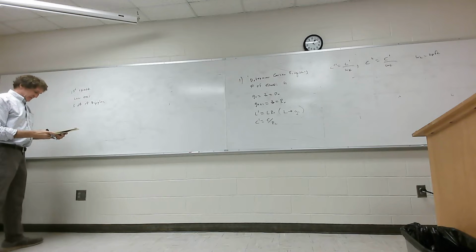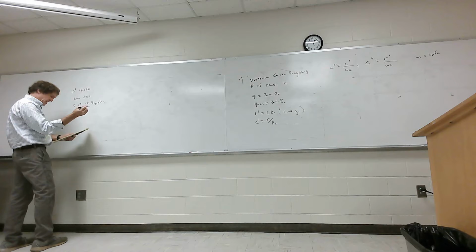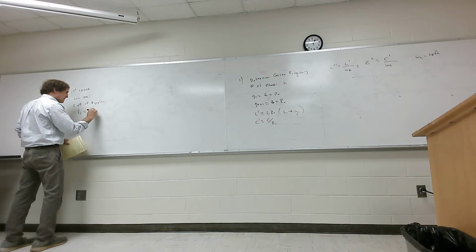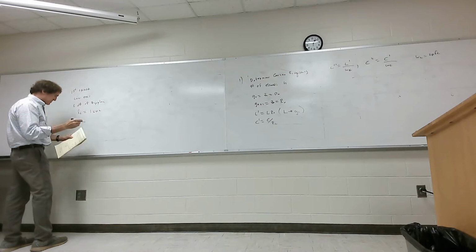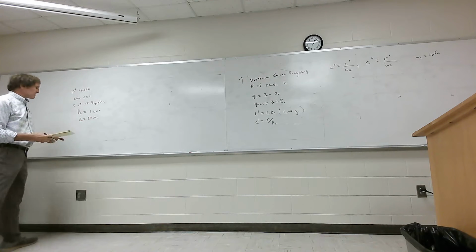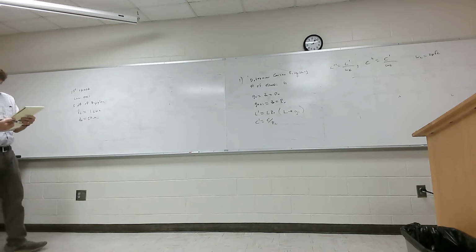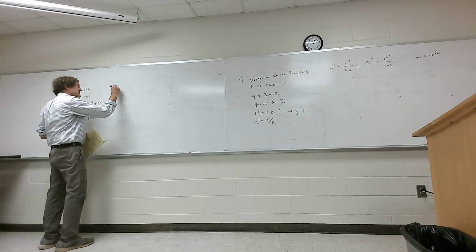I'll explain what ripple is in a second, but you probably can guess. And he wants the cutoff frequency for this to be 1 gigahertz. And the characteristic impedance of this is 50 ohms. So it's 50 ohm source, 50 ohm load. First order means one element. When they say order, it's the value n, so it's just one element, which is nice.